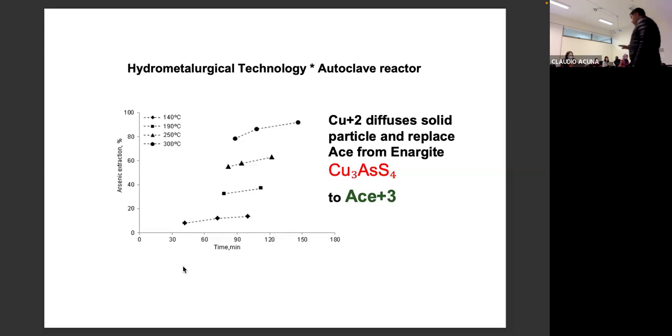No, I'm not kidding. If you review autoclave reactors, you will see very often they don't start from 0, and that happens because it's a batch test: you put in the sample, you start heating it up, and when you reach the temperature, 200 degrees, that will be your initial time 0. But the reaction started a long time ago. As soon as you put the sample in, you have a heating curve that you take into consideration.